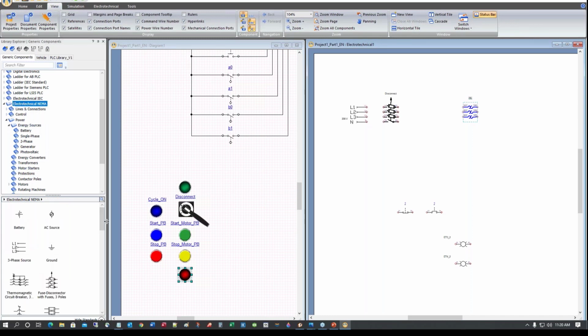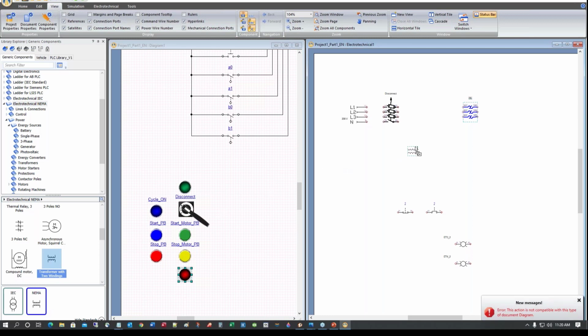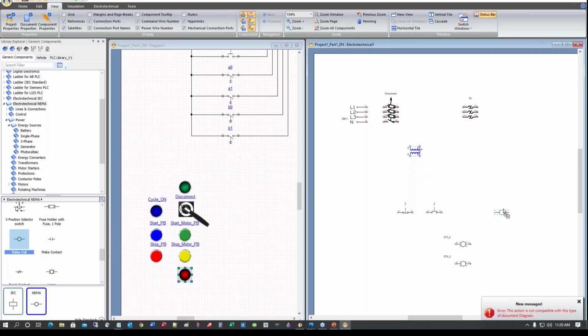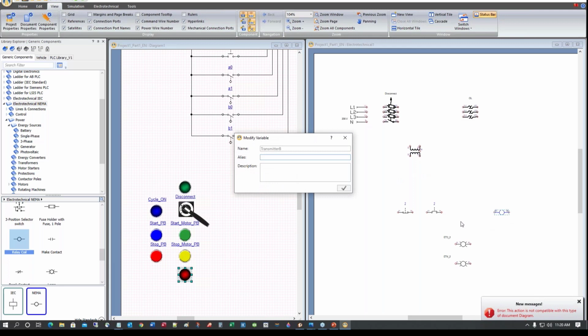So we probably need to do the controls, a transformer. So we need a transformer. And then we need a relay. You need a relay, control relay coil. We need one over here just to start the motor. So this is, I'm going to call it control relay forward,